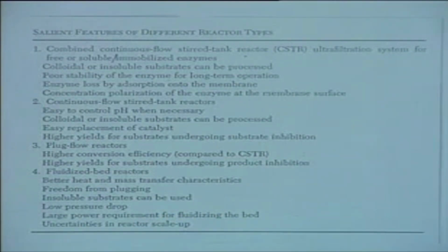Pressure drop is another problem in plug flow reactors, because if we want to eliminate some of the problems associated with internal pore diffusion, the particle size has to be reduced, and reduction of particle size means increasing pressure drop across the bed, which ultimately puts an economic barrier in terms of higher energy consumption for feeding the substrate.